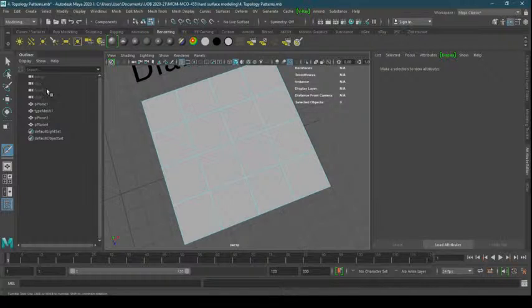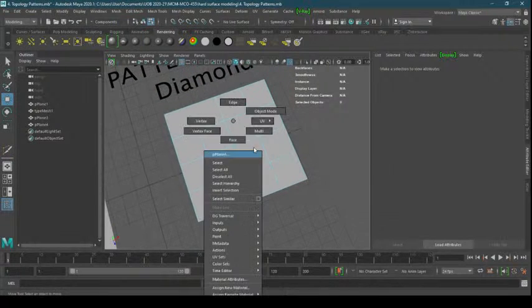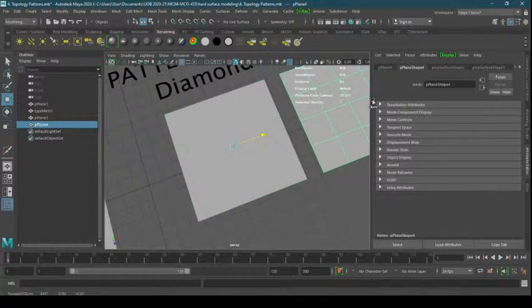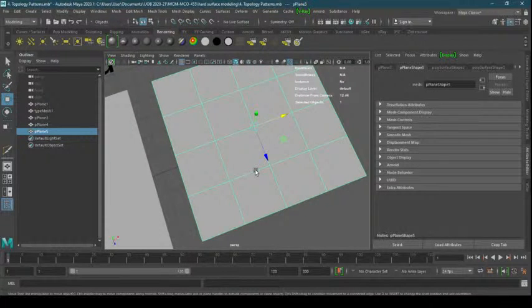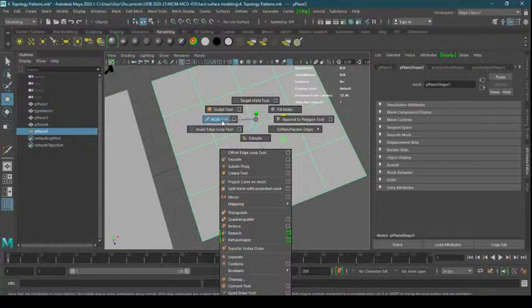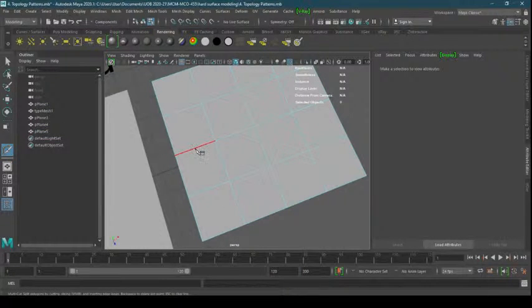Because if I do, for example, let me take this one here, just to give you an example, right click and take the multi-cut tool. If I press Ctrl, or in the middle, and in the middle here, enter, you can add a vertex in the middle.